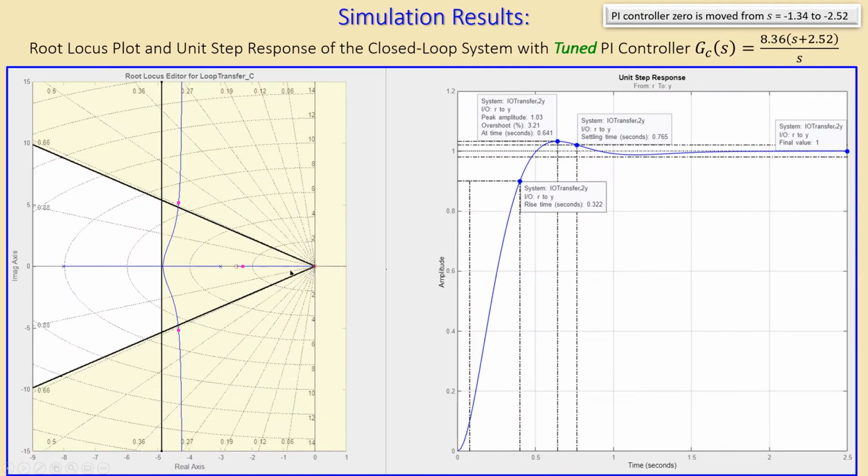We have the root locus plot with the poles given here, and this yellow region is where it is not allowed to be in the ideal case where you have just only 2 poles and no zeros at all in your system.